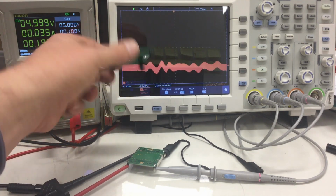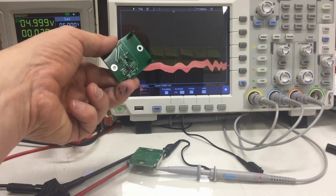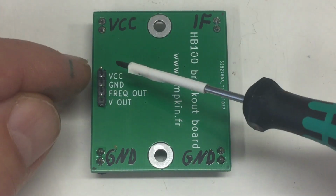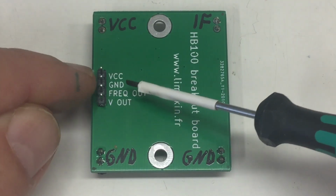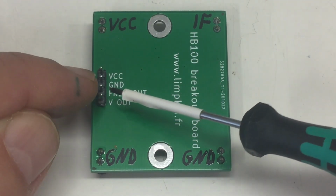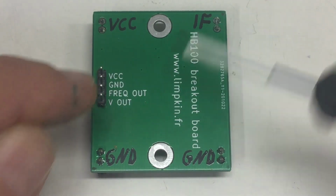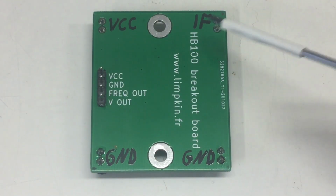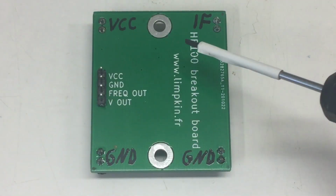And these breakout boards are supposed to make sense out of these signals. Connection-wise, these boards are simple affairs. You have a pin header here at the back, you feed in VCC 5 volts, your ground connection, and you have a frequency out that should give you the processed, we will see that in a second, intermediate frequency signal from the HB100 radar module.